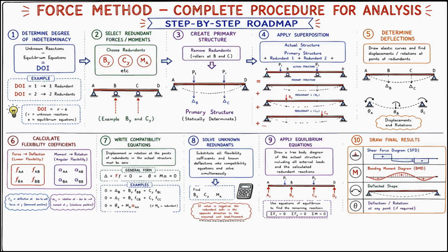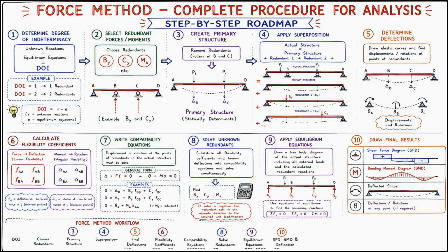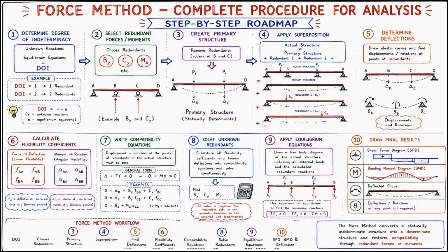The beauty of the force method is that it converts a statically indeterminate structure into a statically determinate structure, and then restores the removed reactions using compatibility conditions. Once you understand compatibility, flexibility coefficients, and superposition, the entire force method becomes very straightforward.